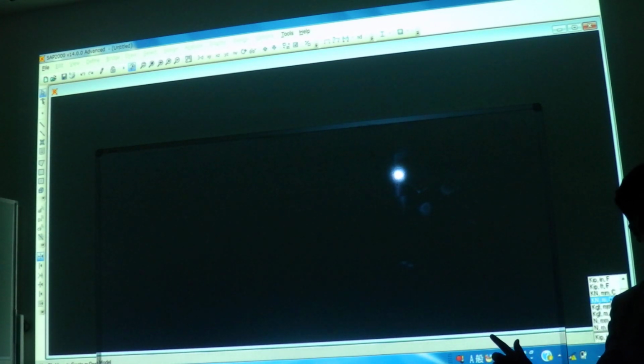You can change the units on this box here. There are different types of units: kip inch, kip feet, kilonewton meter, newton millimeter. The most common units in the SI system are newton millimeter. But for the bridge modeling, we can use, for example, 20 megapascal. What does it mean? It means 20 newton per millimeter square. 1 newton per millimeter square is equal to 1 megapascal. Am I right? Yes, sir.